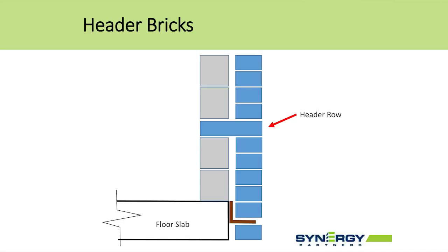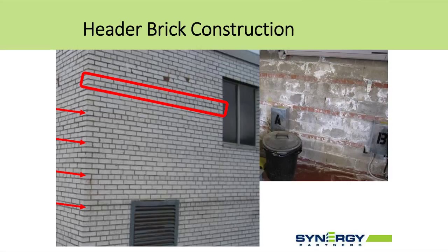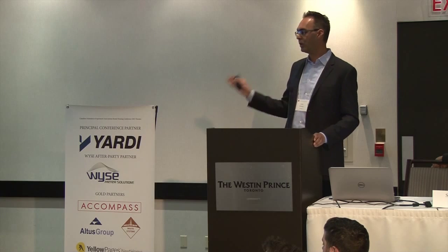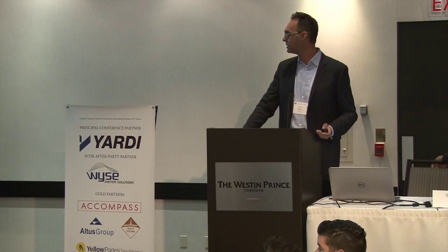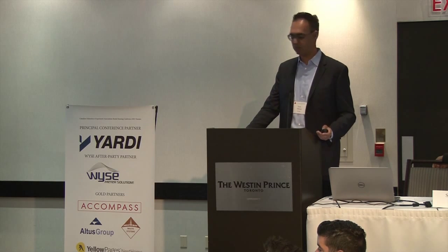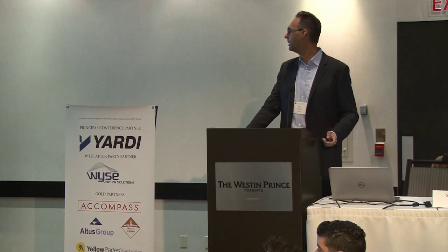And by turning the outside face brick and embedding it in the backup wall, which you can see in this photo here, you can see the red bricks, how they're tied into the concrete block. And on the outside, this is what you see. You just see a row of bricks which are turned on end. That's what forms the connection and basically combines to form a monolithic wall structure. No longer used. There are inherent problems with the design, but you still find it in older buildings, sort of 1970s vintage, but not typically later than that.